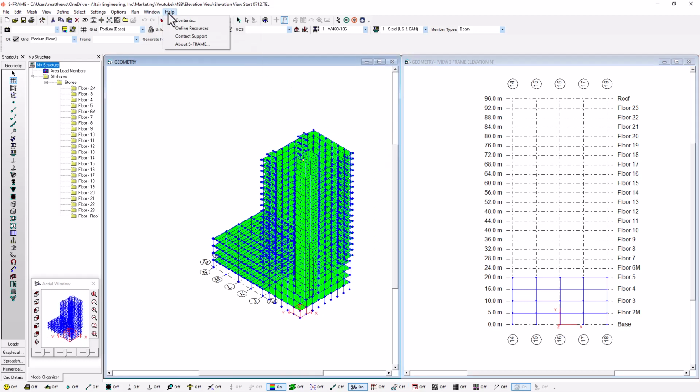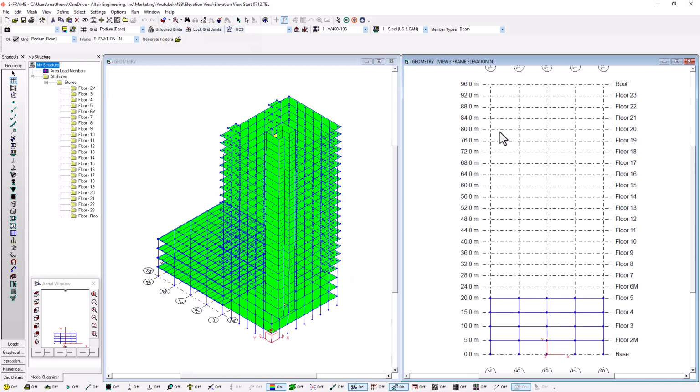And just like before, we can go in and we can say, let's go to the window tile. And what I want to do is add some eccentric steel bracing to this end frame of my podium. So I'm going to use the member definition tool. And because I'm in the active plan view, or elevation view rather, I can specify the 2D patterns that are being used, and I actually have this set up already for inverted V-brace. And when I select the inverted V-brace, I have the option to define an eccentricity ratio.